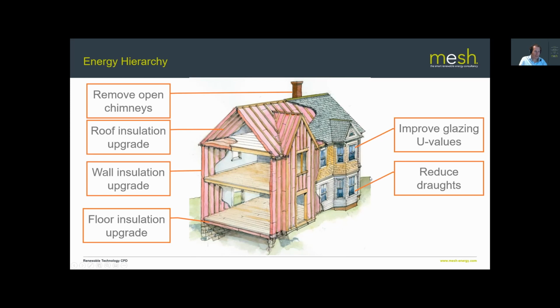Good well-fitting windows can reduce heat losses a huge amount. But going for double glazed or triple glazed units can really help improve the U values. If you replace an old single glazed unit with a modern double glazed argon filled or vacuum filled unit, you might be able to reduce the U value of that window by a factor of nearly 5. That's a huge saving, and it will reflect in the comfort of the home as well, not just in the fuel costs.